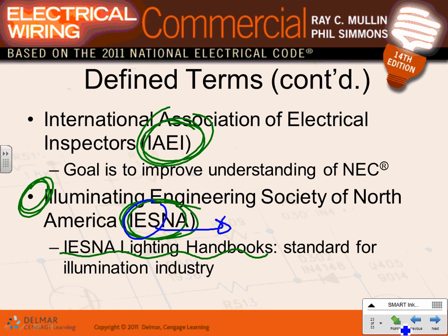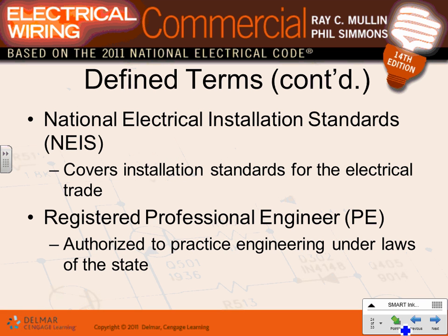Every fixture right above your head, you're going to be downloading an IES file for it. It's like a DWG file. Remember the DWG file, right? Or the doc file for all these different files. The standard in the industry for lighting is the IES file. So if you want to have any fixture and do calculation in there, you're going to ask 2 questions. Number 1, get me the IES file so I can run it and give me a short. So if you get the IES and the spec about this lighting, you got everything you need. Okay, so these are 4 lights.